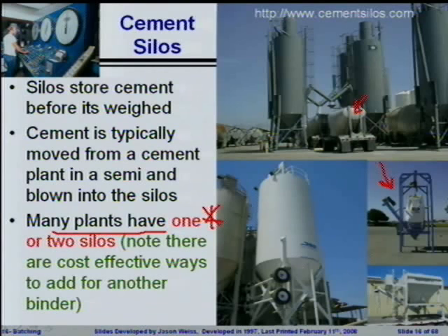Make sure that when your fly ash is delivered, and when the cement is delivered, they're hooking it up and putting it in the right spot. Many places you will actually see padlocks, and the driver needs to come and get the correct padlock for whatever material they're dropping off. The idea there is to minimize the potential for mishap by putting fly ash or cement in the wrong silo.